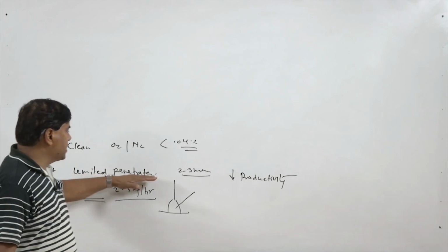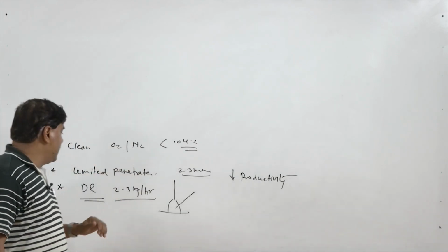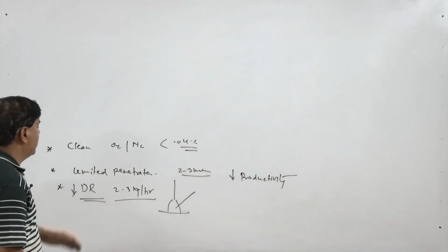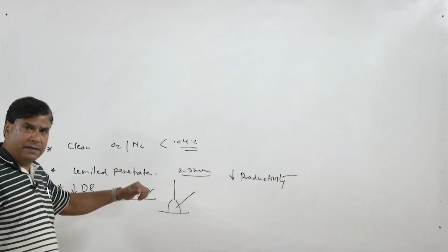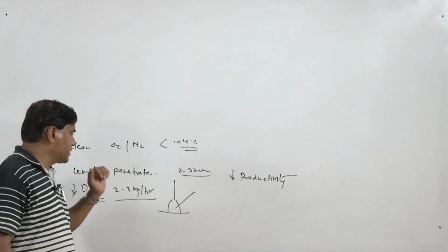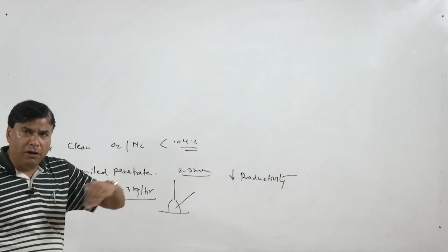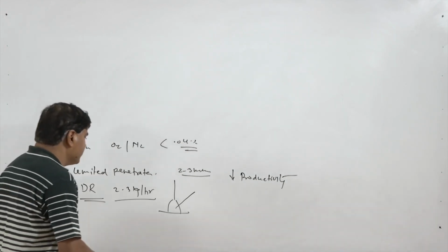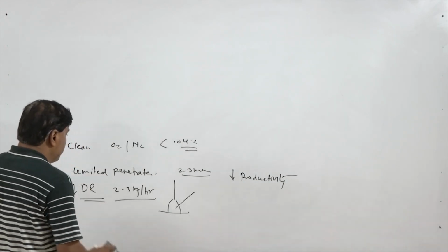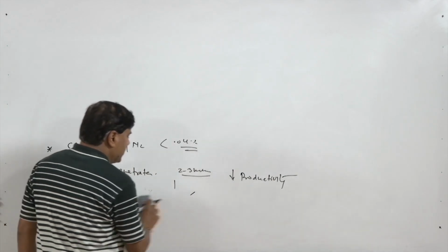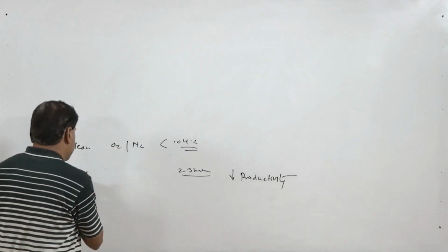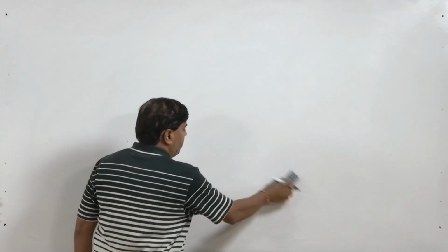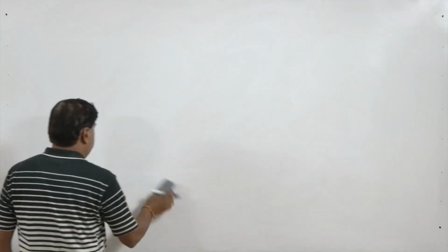So, limited penetration is one aspect, and the reduced deposition rate is another negative side related with the process, because of which it takes very long to complete the weld joints, especially in case of thick welds. So, various efforts have been made to modify the conventional gas tungsten arc welding process in order to overcome these points related to this process.